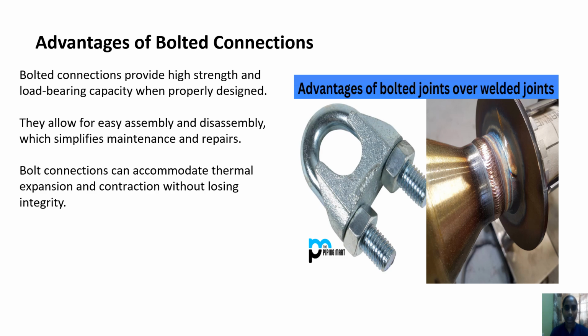Advantages of bolted connections. Bolted connections provide high strength and load-bearing capacity when properly designed. They allow for easy assembly and disassembly, which simplifies maintenance and repairs. Bolted connections can accommodate thermal expansion and contraction without losing integrity.